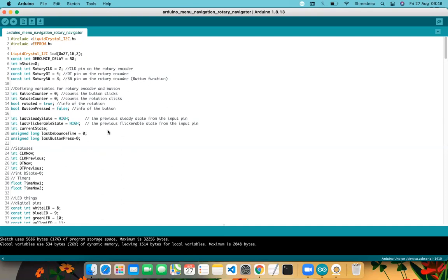If it's not a switch, for example, in place of a rotary encoder, if there is any sensitive sensor or device which needs to be monitored, which needs the processor's attention frequently, it's better to connect it to one of the interrupts without much hassle. Once you connect to the interrupt, the moment the condition is satisfied, the function you have written inside the interrupt service subroutine will be called by the hardware, by the Arduino system, without any physical intervention. That is what we have done.